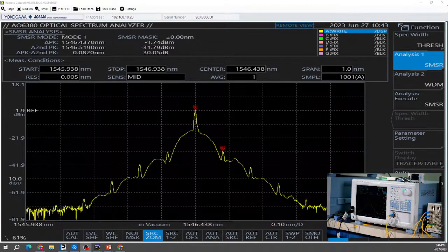As I was showing earlier, it's great for showing the peak wavelength accuracy of the device, but it's not so great when you need the dynamic range required in some of these cases, like showing the OSNR on signals, for example, with very low noise. So we really don't offer that capability with the interferometer-based wavelength meter.